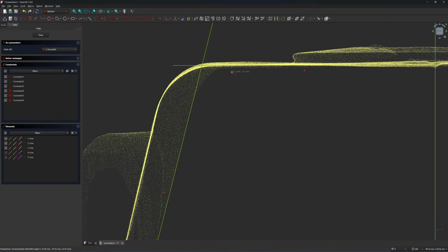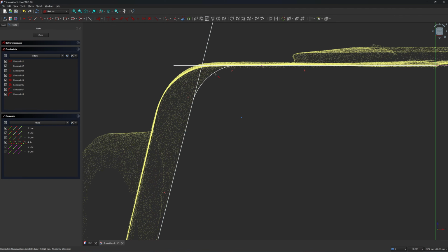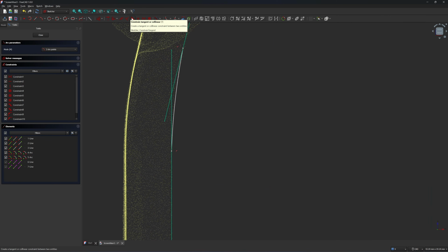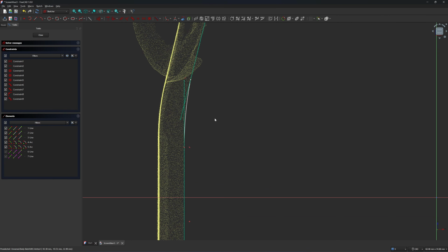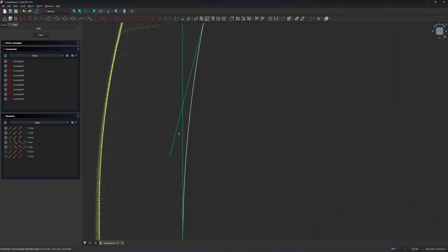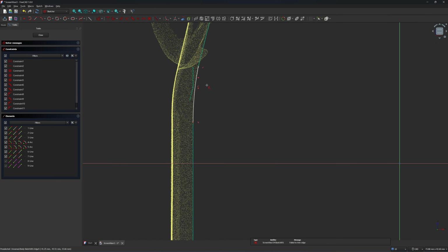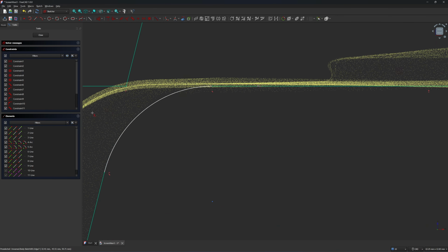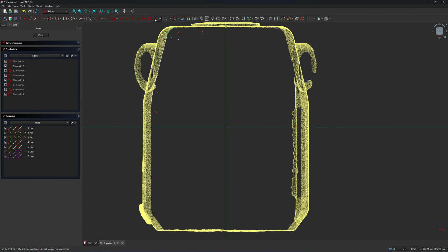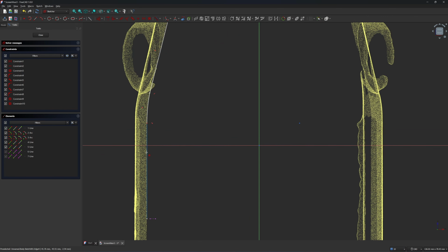And then I'm going to make a 3-point arc, put it into tangent. Okay, now it's tangent. Another 3-point arc. Okay, put it into a tangent. Okay, now it's right. Next step, I will trim it using this one. Trim, trim, trim, and trim. Okay, let me remove this. Okay, let's lock everything so we don't have to worry about accidentally moving it.